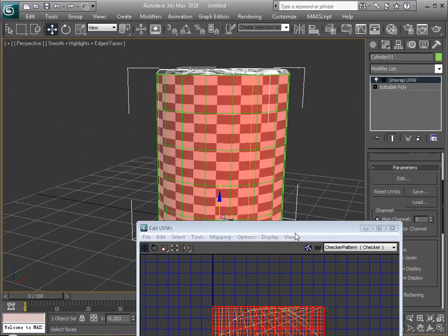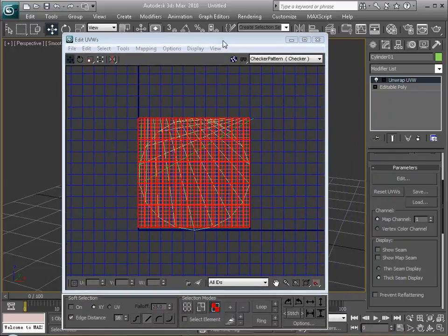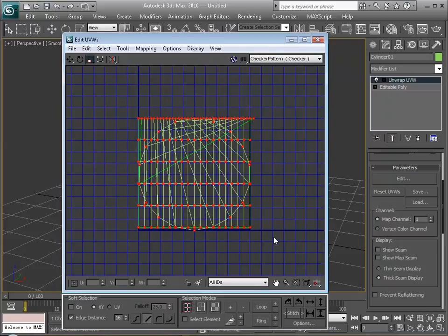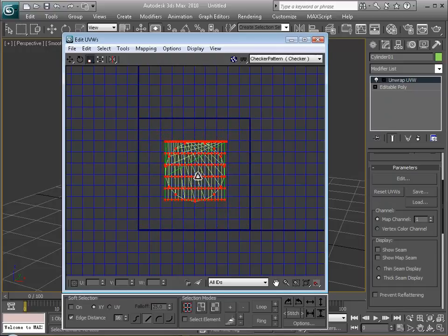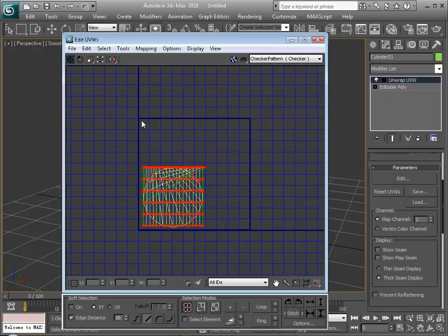Right now the side is okay. What I need to do is resize it. Now I will select the UVs and resize it to make it smaller, to the other side, because we need to export this whole square into Photoshop later. So we make sure that everything must fit. Just make it smaller.